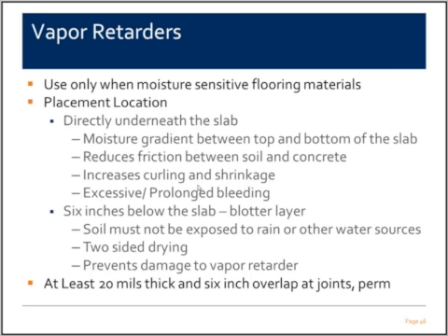First and foremost, I typically do not recommend that vapor retarders are used when there are no moisture-sensitive flooring materials that are going to be applied to the slab. If we don't have moisture-sensitive materials, I do not recommend using vapor retarders.